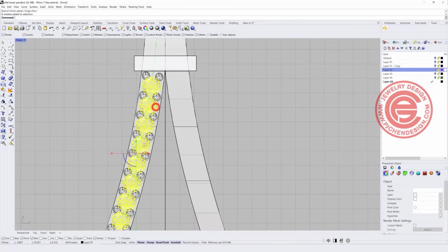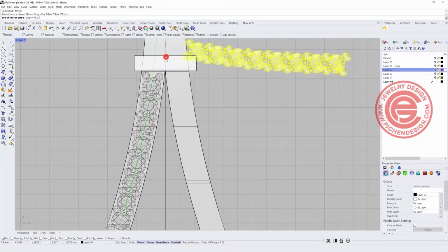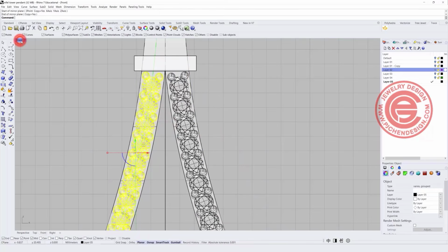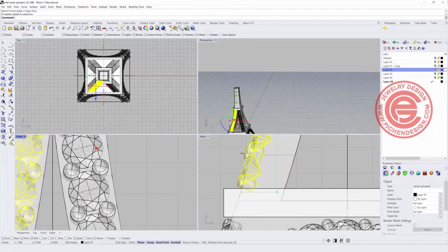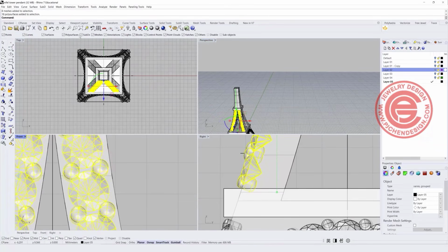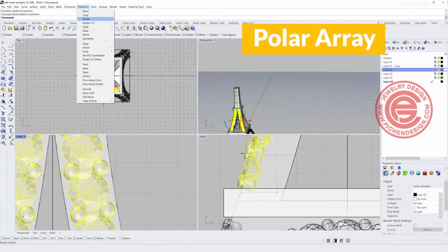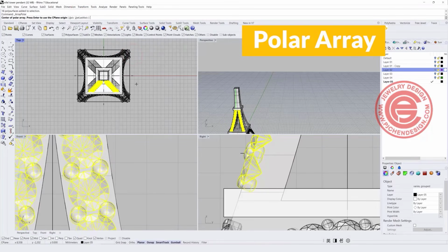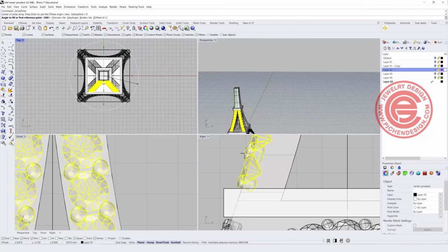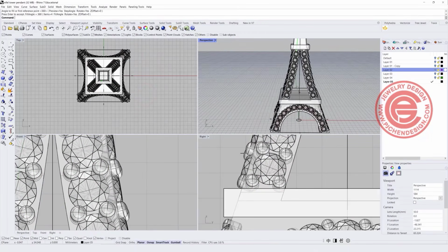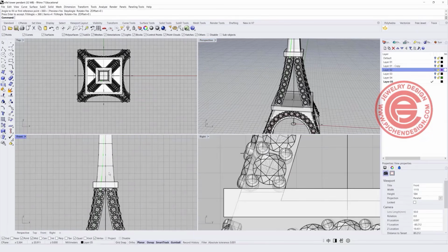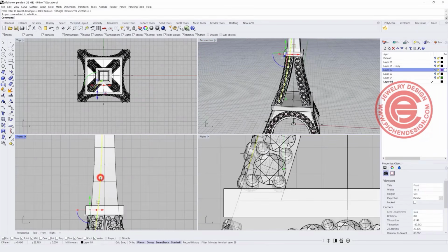All right, so first of all, let's pick up a stone and the prong, and we just want to mirror to the other side. And if that looks all right to you, what we want to do is pick up the other side right here. Coming into my top view, we want to use the polar array, and we want to snap into the 0, full circle for 360 degrees. Then we'll have something like this. All right, the very last part is we need a line right in the middle.